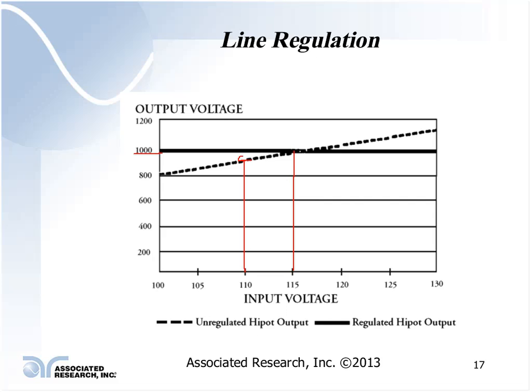I've had customers say, well, hey, I'm testing products that are both 115 volt and 230 volt input voltage, so my test potential may be different for these two products. Rather than setting up two different test potentials, I may test everything at the 230 volt input voltage level.